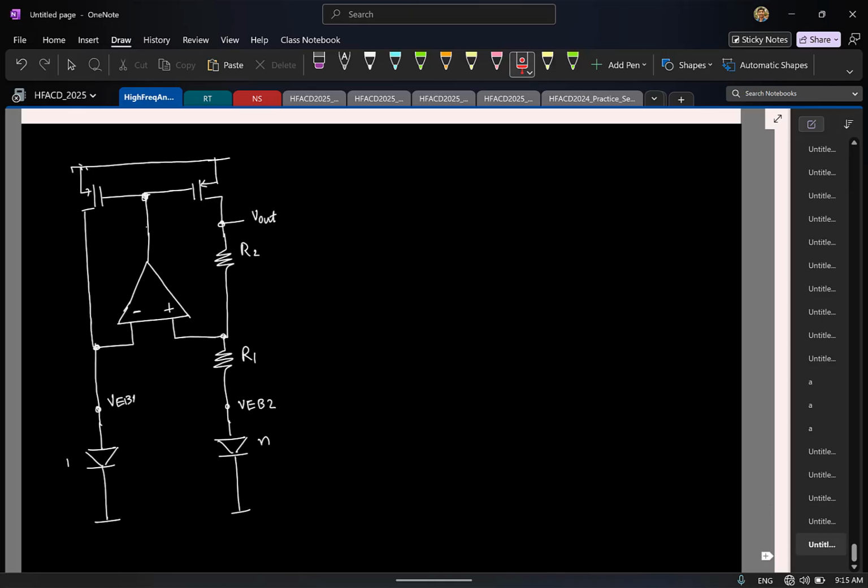Cool. Now, like I told you, this is a very commonly used circuit. And what is this output voltage approximately? Let's say 1.12 something. So if this voltage must be 1.12 volt, how much should the supply be at least? At least more than 1.12 volt by some minimum overdrive, so at least 1.2 or 1.3 or something higher. So this puts restrictions on using this at low voltages. When the supply is 1 volt or so, it's difficult to use the circuit.